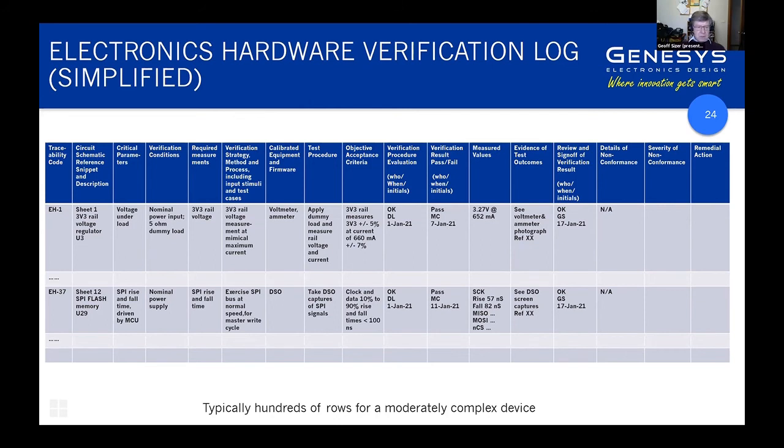Many engineers attempt to say, though, if the device works and the memory works and the SPI bus is fine, tick, everything's good. If you're going to do thorough verification of that device, you will look down at the detail of the SPI bus. So is that SPI bus operating effectively? So the rise and fall times of all the signals within the specification for SPI when using that bus for the specification of the devices that are on that bus.